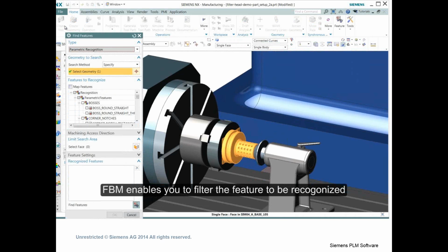Feature-based: simply select the part and select the desired type of features we are looking for. You may filter them just separately or find all features on the part. Here we will unselect grooves and we will just select the hole operations on the part in this demonstration.